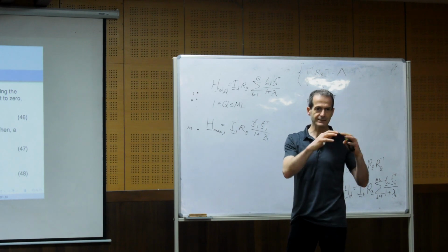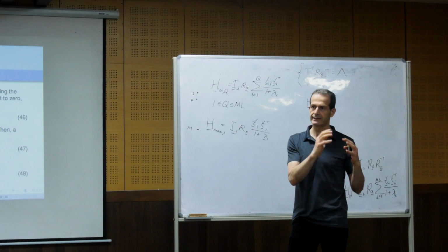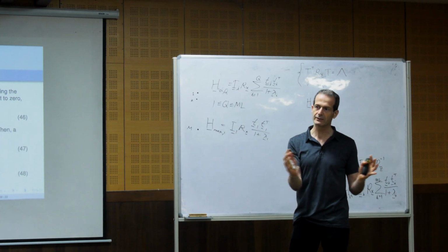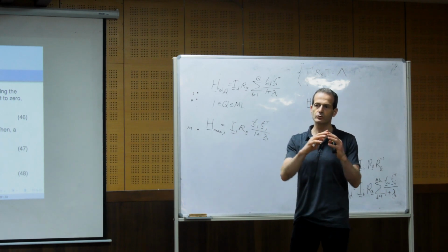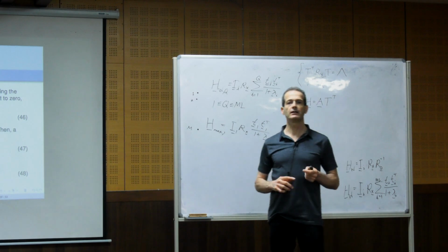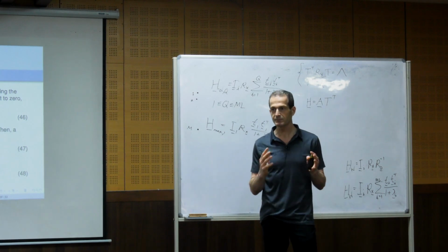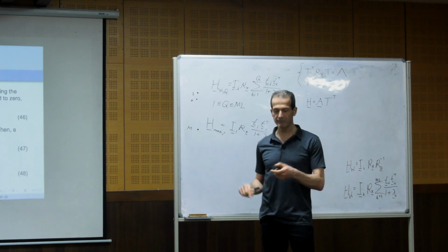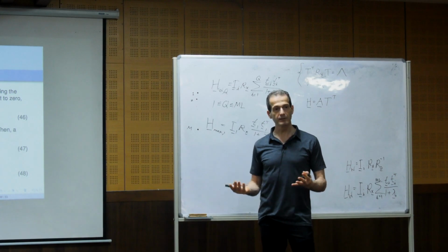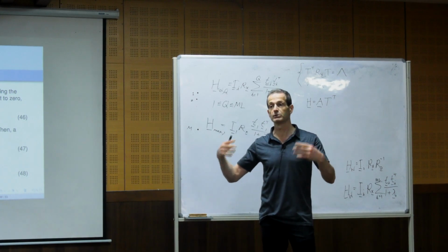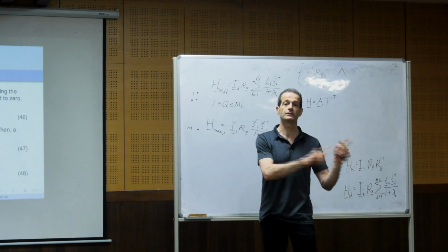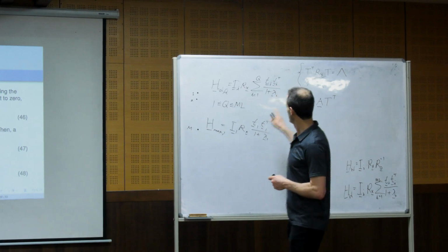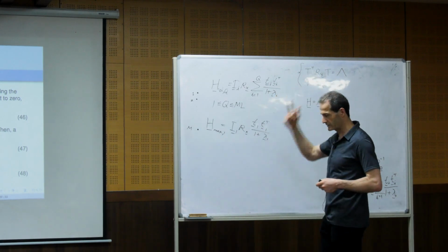So the signal subspace is the most concentrated in that transform. Once we have such a transform that we can concentrate all the signal components into the smaller dimension of the subspace, we can have good separation between them, and then the MVDR will be able to suppress as much as possible noise without any distortion to the desired signal. Okay? Makes sense. That's why we work in this transform domain.